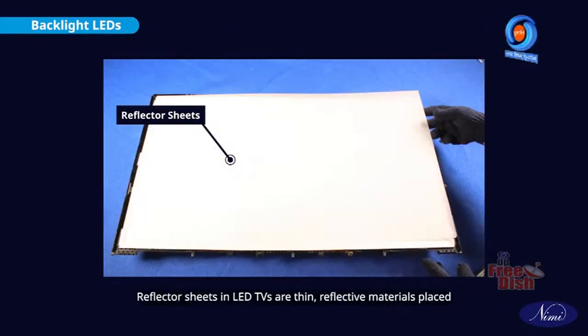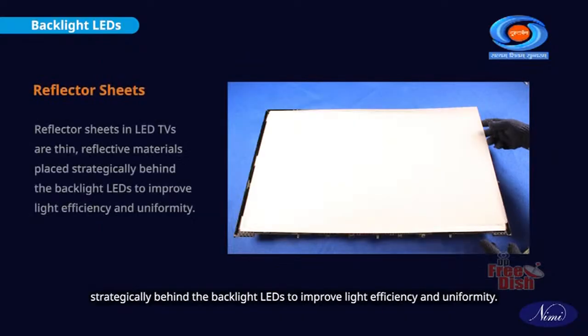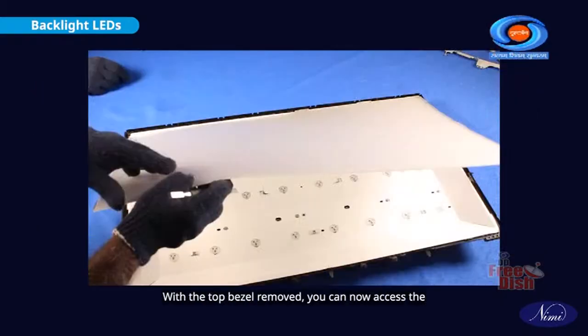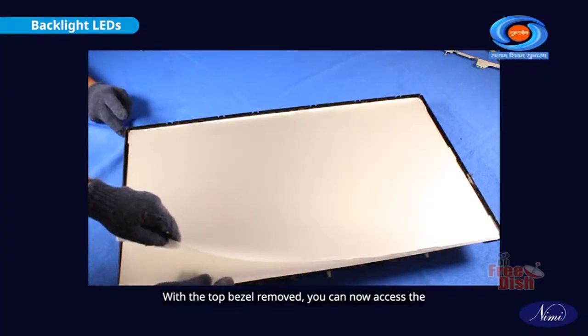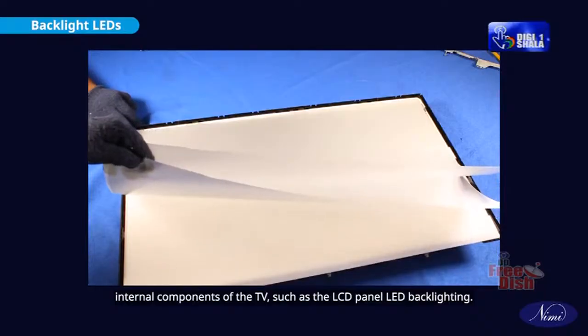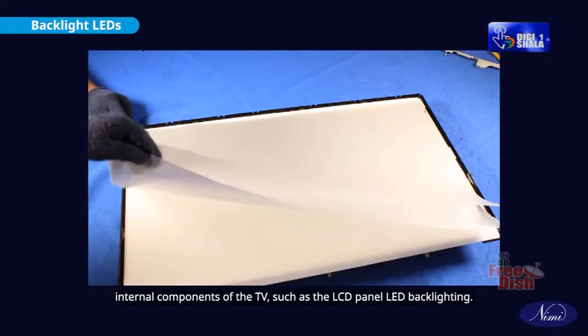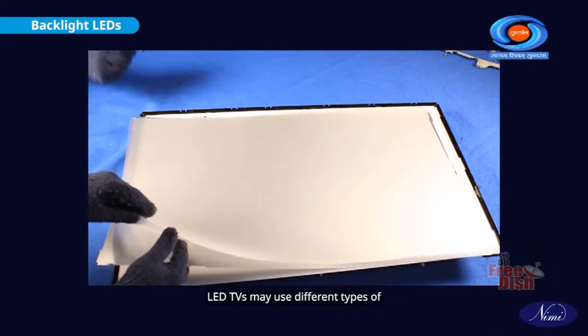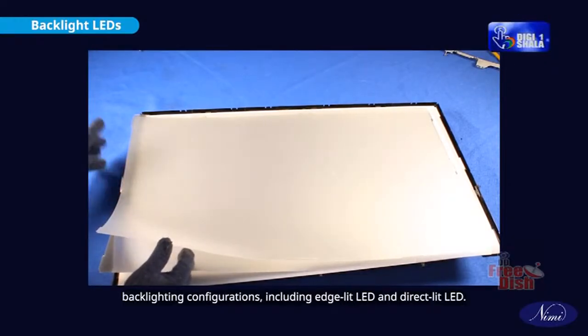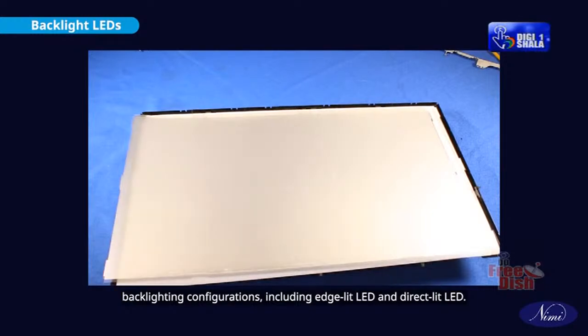Reflector sheets in LED TVs are thin, reflective materials placed strategically behind the backlight LEDs to improve light efficiency and uniformity. With the top bezel removed, you can now access the internal components of the TV such as the LCD panel and LED backlighting. LED TVs may use different types of backlighting configurations including edge lit LED and direct lit LED.